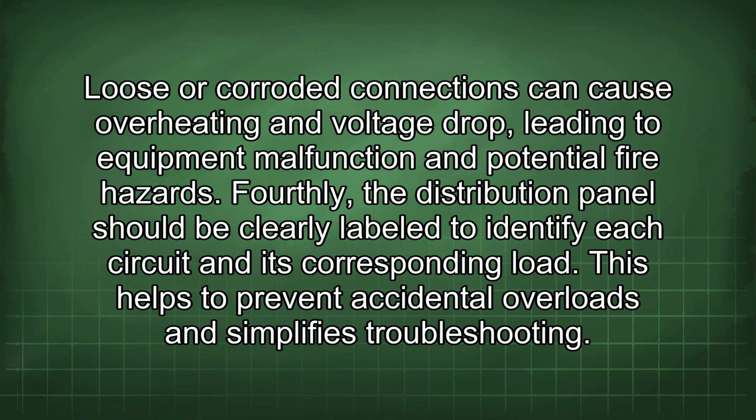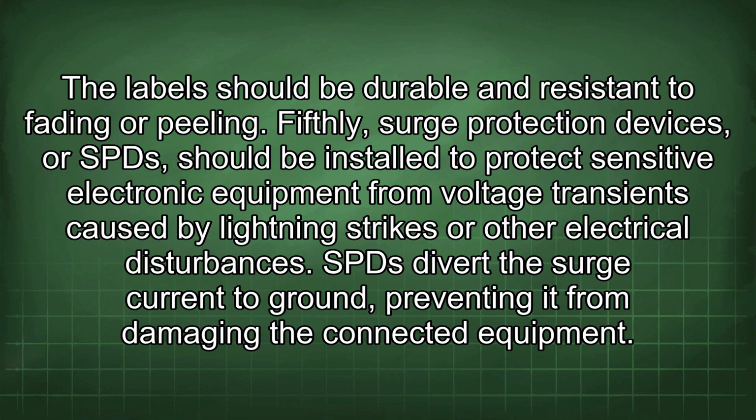Fourthly, the distribution panel should be clearly labeled to identify each circuit and its corresponding load. This helps to prevent accidental overloads and simplifies troubleshooting. The labels should be durable and resistant to fading or peeling.